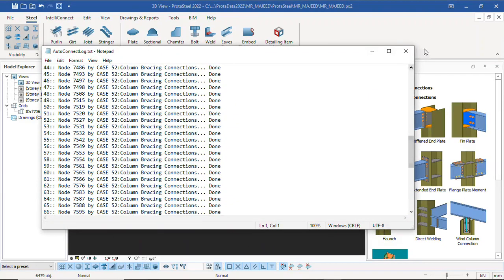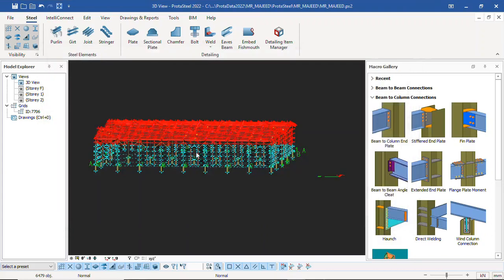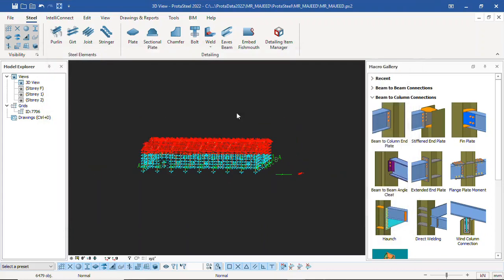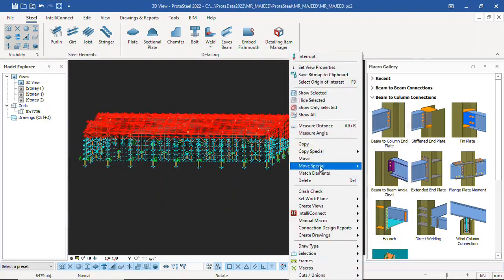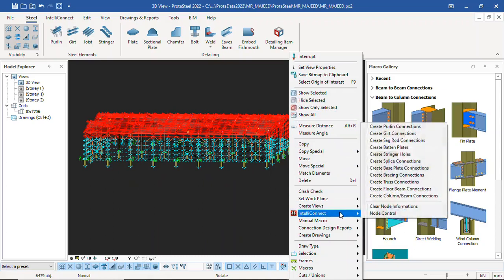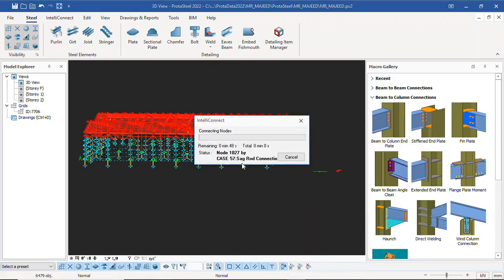Okay, your vertical bracing is done. Now let me do sag rods. Do the sag rod connection, interconnect the sag rods, create sag rods. This project is a live project. It's work that is pending to be executed, so I have to do everything that's supposed to be done.